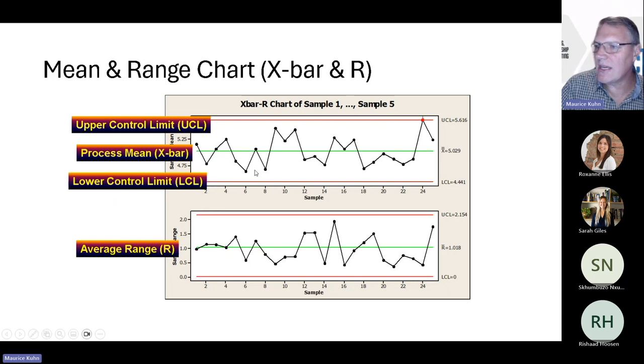When we run control charts, then this is pretty much telling us certain things. You know, it tells us where our average is. It sets our control limits, and one of the tests is, is our process going beyond our control limits? That's one of our 8 tests. And these control limits are set at 3 standard deviations away from the mean, where I'd expect to see almost all of my data between my control limits. That is where they set. So if any point goes outside of those, that's statistically normally an indicator that something funny is going on here. We need to go and investigate what happened there, because it's not common to the process. But like I said, that's only one of the 8 tests.